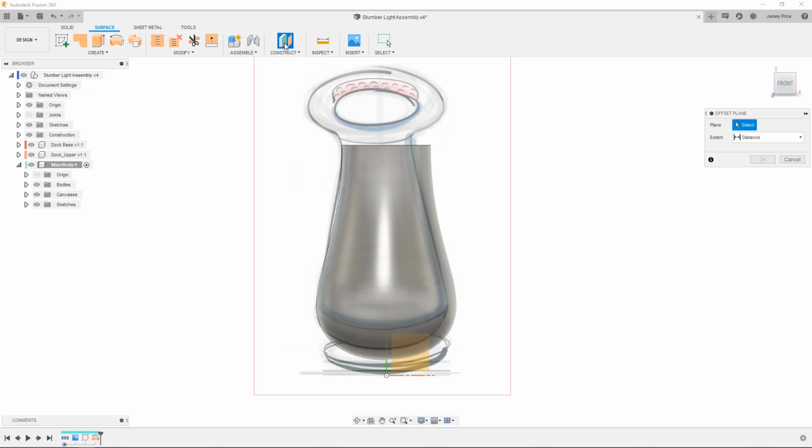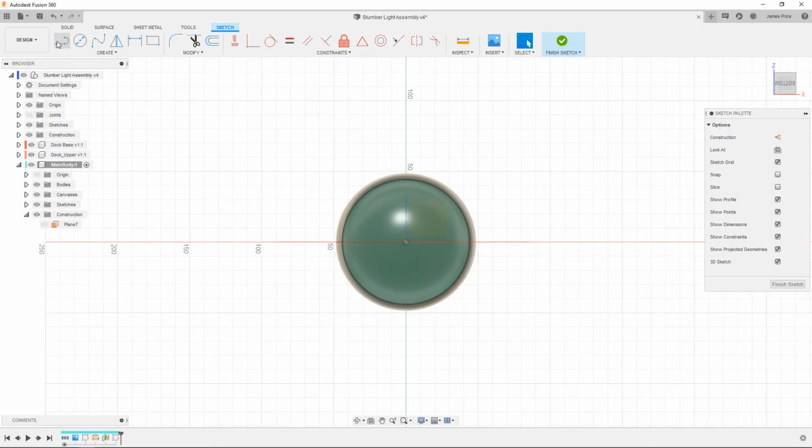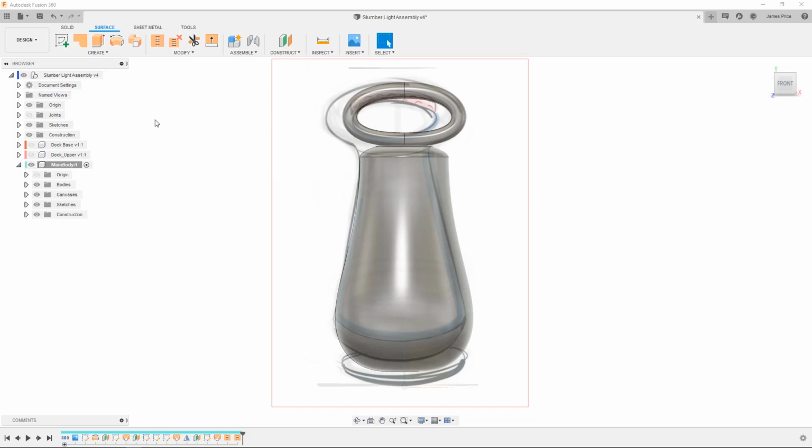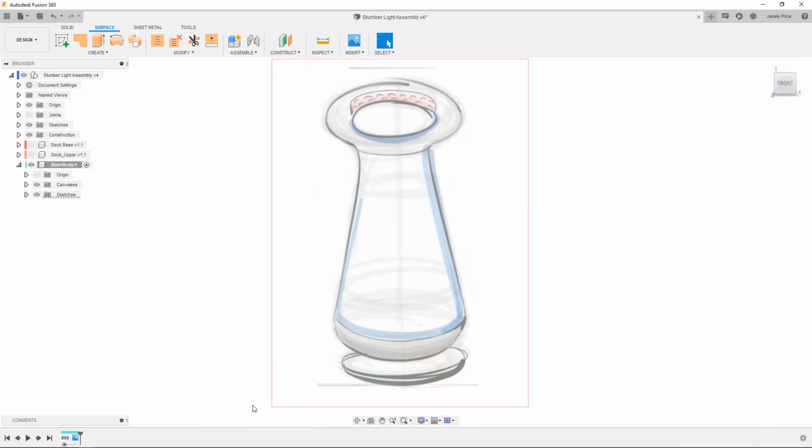Then, I might create a construction plane and sketch another profile, then loft the two, being sure to set my curvature and its strength and any guardrails if applicable. I would repeat the above process and edit the design as necessary until we have our general form, then stitch the surfaces together, allowing me to further remove any unwanted surfaces until we are happy with the result.